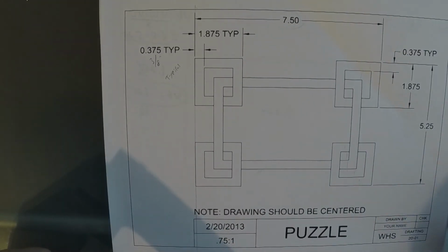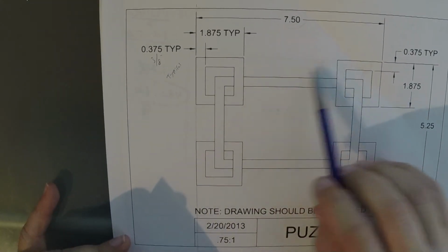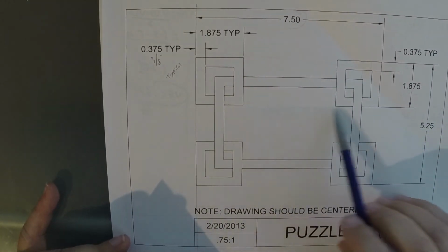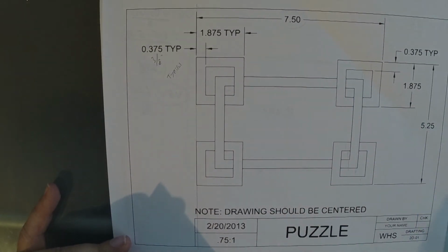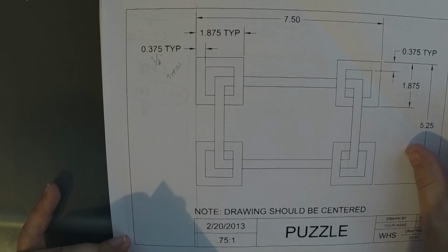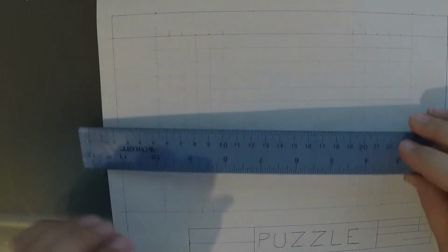So that's kind of like the big setup phase. We're now ready to start interpreting which lines we want to keep and which lines we don't want to keep. And remember, we should not have to erase a construction line. So yes, you drew lines all the way across inside of here, but you don't have to erase them because they should disappear. If you photocopy them or if you hold your paper at arm's length away, they're really light. If they're too dark, then yes, you're going to have to erase those lines. But the goal is not to erase.